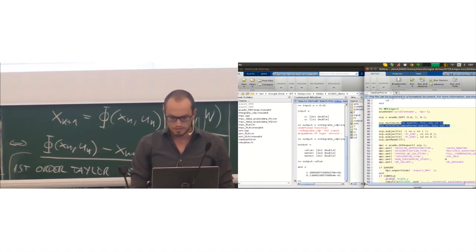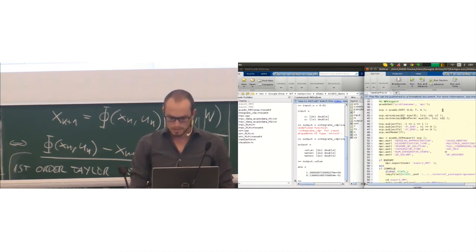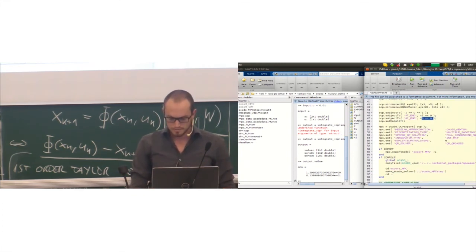And then I also have a terminal cost. So that's the minimize LSQ N term, the terminal term basically. And LSQ stands for least squares. So that's it for the objective. And then I have some constraints. So subject to basically is all constraints you have. In this case, I also set the model. I have some bounds on u, with similar syntax to YAML. And this "at end" means that it's only at the last node, where I say that I want both states to be equal to 0. So it's an equality terminal constraint.